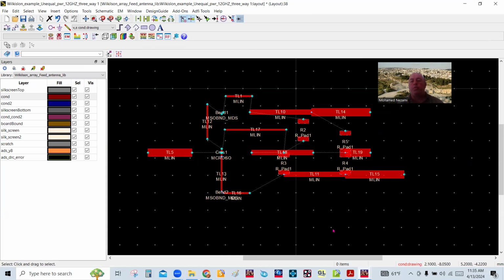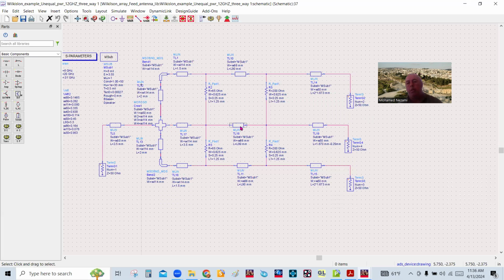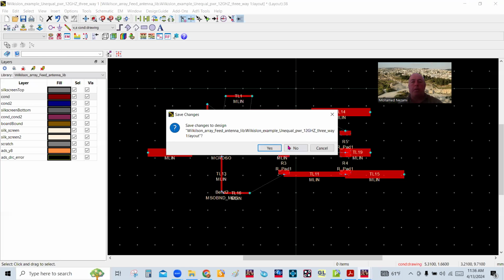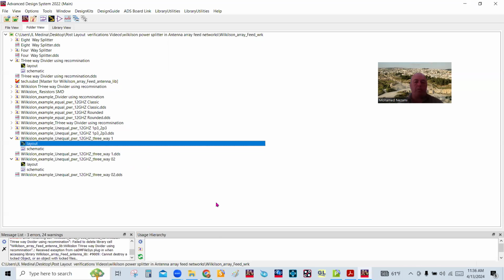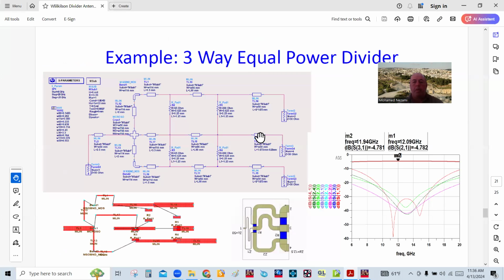Now, once you do this, of course, you need to EM simulate this. You need to come in and attach boards to this and run an EM simulator rather than a linear simulator with S-parameter based, because it's not anymore the same thing. But this is a good starting point. I'll leave that as an exercise for my trainee students in my workshops.